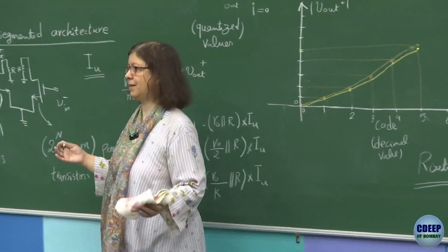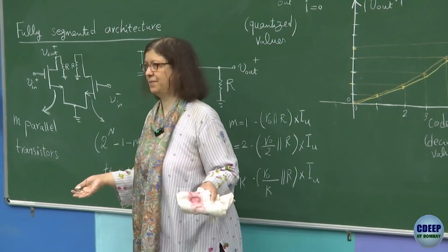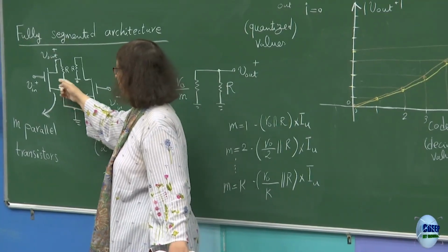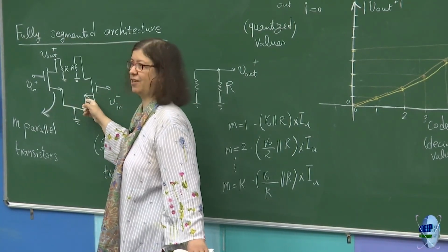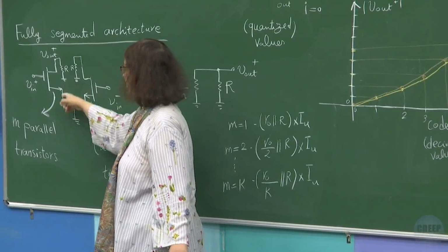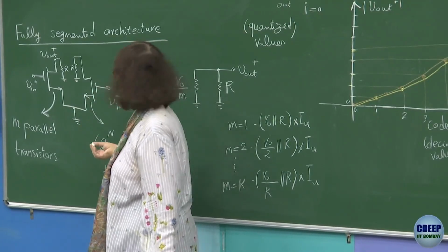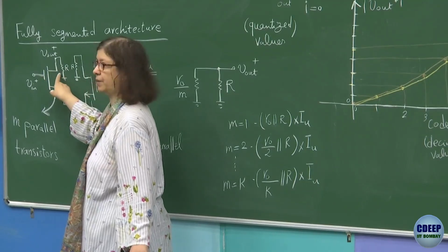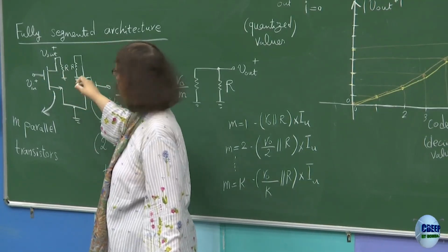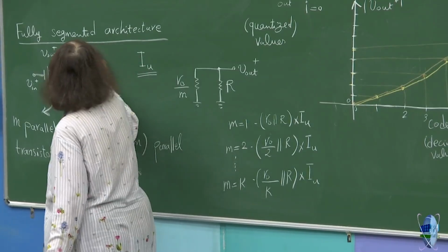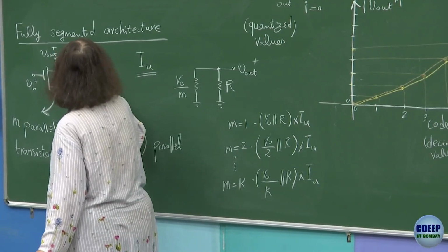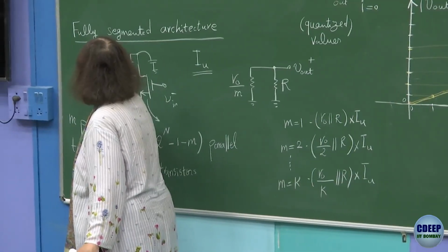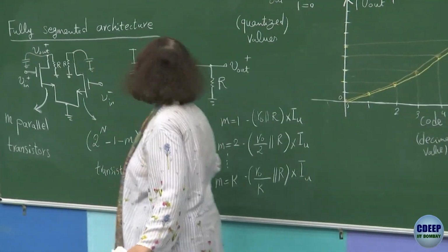Now, going back to RO. RO has an inverse relation with current in any transistor. And to make it high, you need to make these transistors not short channel. So now you make these transistors long channel. Therefore, parasitics will start showing up here. This is not a resistor anymore. There will also be parasitic capacitors, in addition to the capacitors it will have from the same thing, IOs.